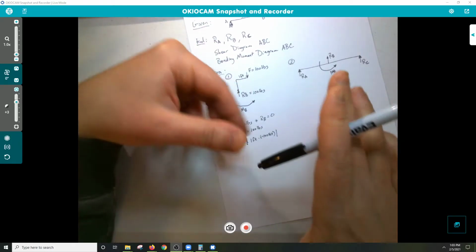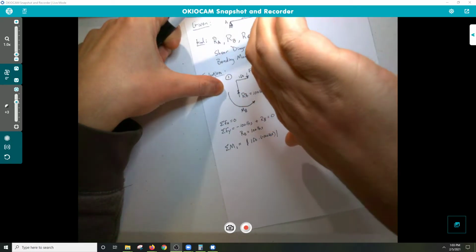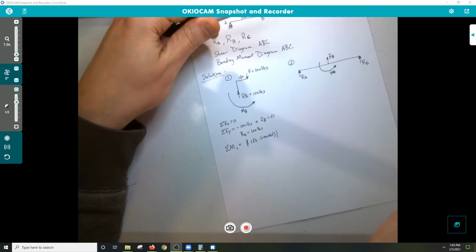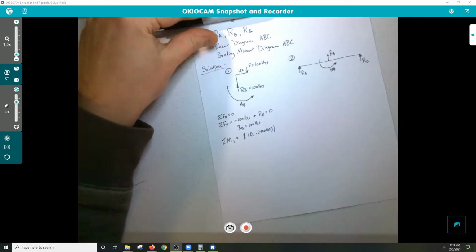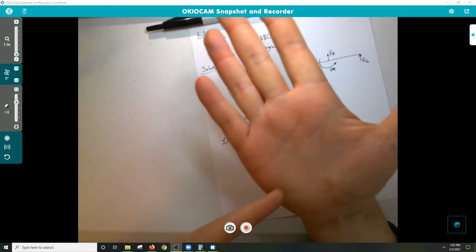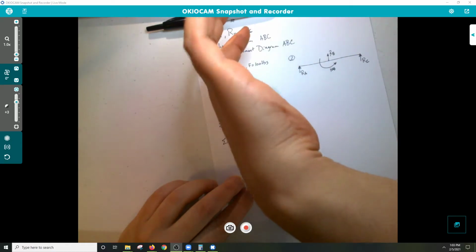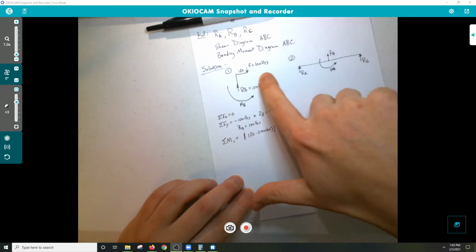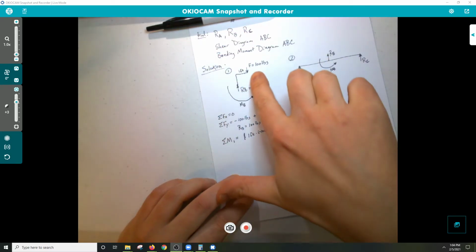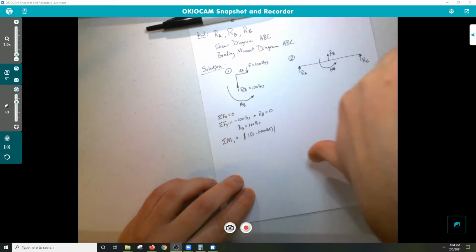So is this going to be positive? And this is where you have to do right hand rule. So again, if we do right hand rule, my way of doing right hand rule, or thinking of it and explaining it, is you think of the axis along your palm, and then I curl my fingers in the direction of the force. So the force that would be essentially causing that moment, and F would cause this curl around, right?